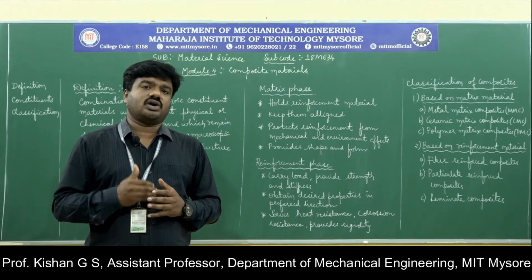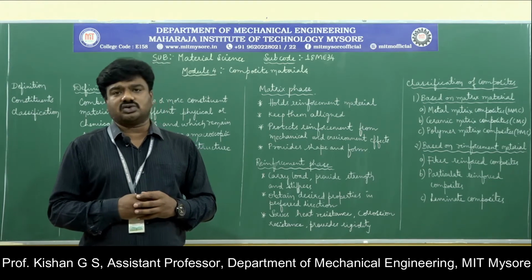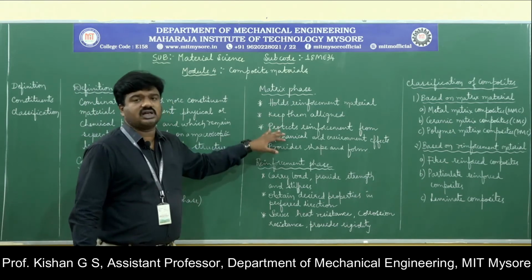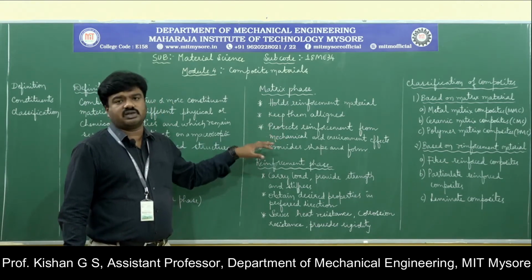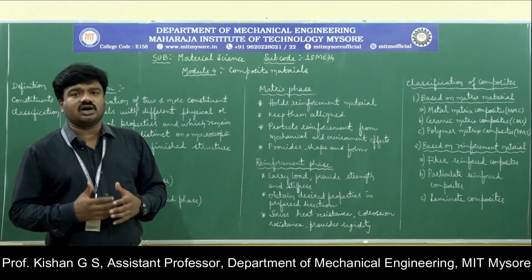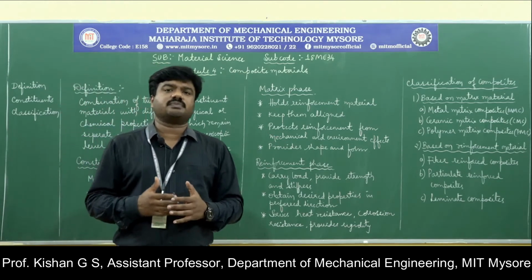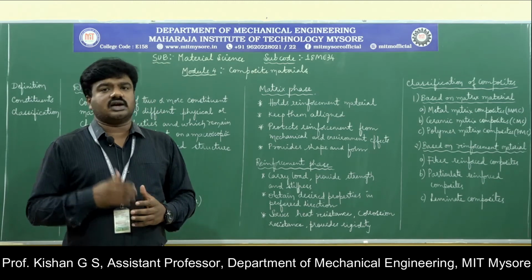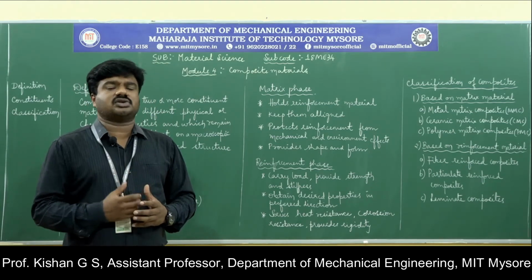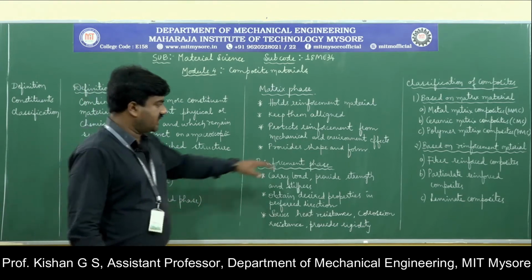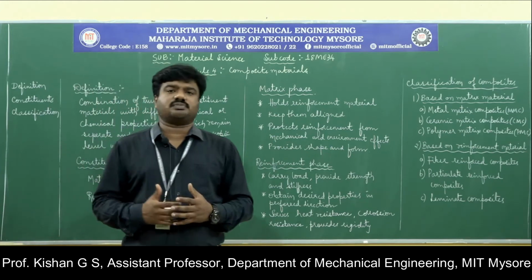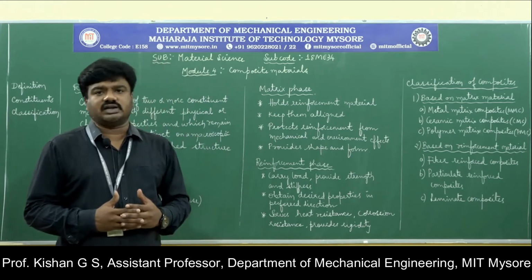So to get maximum strength out of the material composition, the matrix phase protects the reinforcement phase from being affected by mechanical or environmental effects. Mechanical, say for example, additional loading conditions or any type of load conditions that lead to the extraction of strength from the material. Whereas in case of environmental effect, it may be due to the presence of moisture or any other atmospheric content on the material.